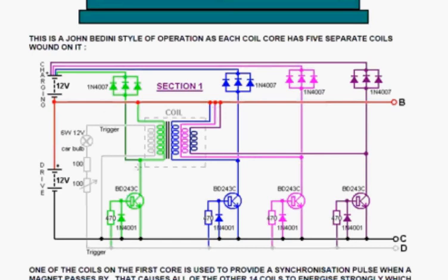But in actual fact, the way that you should do it is you take 3 diodes to lower the impedance of the output flow of energy, and you feed each of those 3 diodes, the set of 3, back to the battery you're charging with its own separate wire. This is quite important. You want a low impedance on your diodes and a separate wire feeding the battery being charged. So here you see there are 4 separate wires going to the one battery being charged.